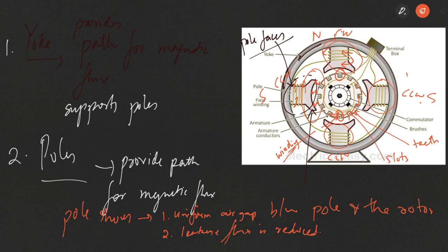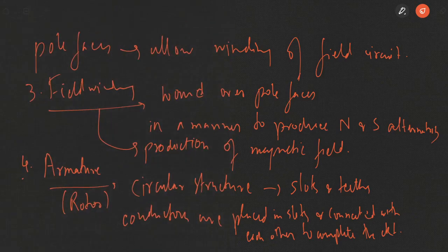So in case of a motor, it is the armature windings that carry the current when placed in the magnetic field. In case it's a DC generator, it is the armature in which the voltage is induced when placed in the magnetic field and rotated by means of any mechanical energy source. So you have armature windings, you have armature conductors. Regarding this, I will shortly tell you how these windings of the armature are wound.